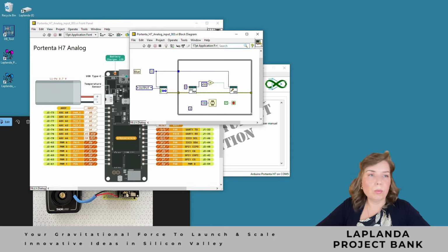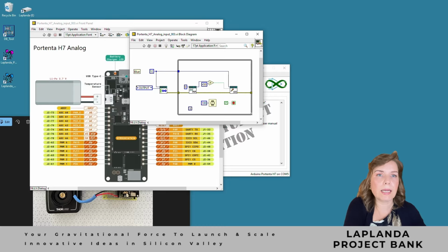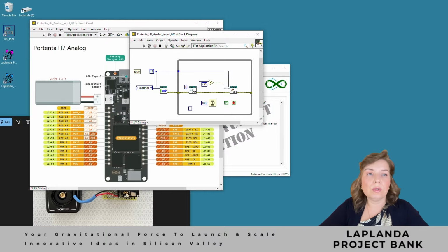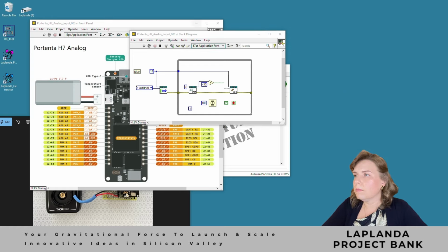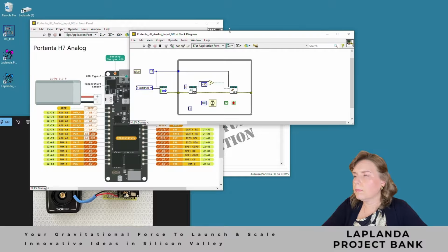I designed the algorithm so that as soon as the light hitting the photosensor exceeds 450, the blue LED turns on. I also decided to add the green and red LEDs and set their trigger levels to 500 and 550. In this case, I'm choosing these thresholds empirically because I don't actually know what the exact limits should be. For my purposes right now, these values are symbolic. I will add 2 more settings for the red and green LEDs and the corresponding digital write functions.